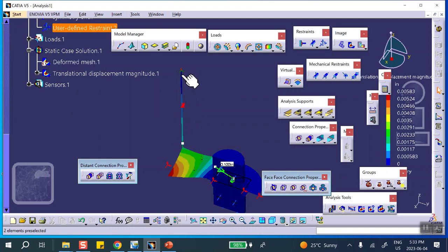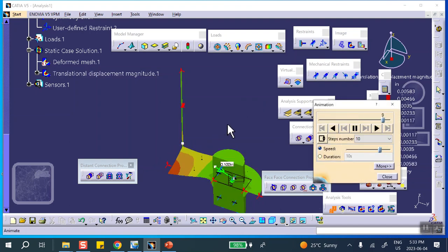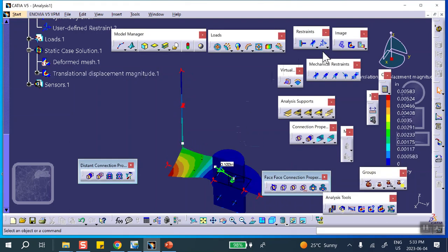that rotation about X and Y-axis. If you make a clamp, it will not rotate about X or about Y, but that may not be the case. They just stretch it. If we had not released the degrees of freedom and that didn't do this thing correctly, it would actually bend. Just to convince you, there we are. Let's go here.